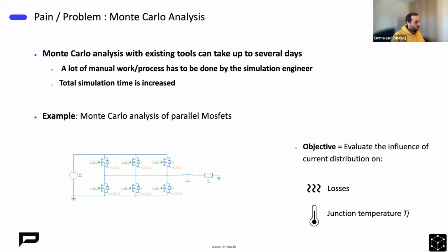You know that it's common to stack MOSFETs in parallel to allow higher current, but because of the nature of the MOSFETs, the RDS(on) value in the different MOSFETs can be a little bit different, right? You have a tolerance, 5%, 10% tolerance. Also, it's a function of the temperature, it's a function of many things. And because the RDS(on) values are not exactly the same, the current will not flow equally in the different MOSFETs.